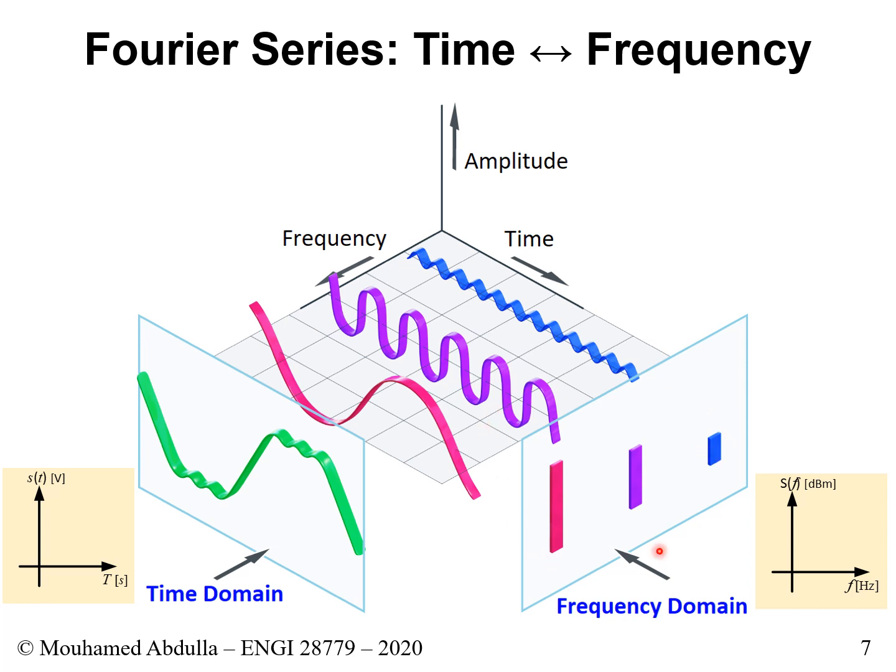This doesn't mean you have this kind of pattern for every kind of signal. For different kinds of signals, you will have different patterns. Sometimes the fourth harmonic is huge and the others are small. Sometimes the first one is huge and then the others are small. Sometimes all of them are large and the middle, let's say the 10th harmonic, is small. It depends on what type of signal you have and how the Fourier series representation is.